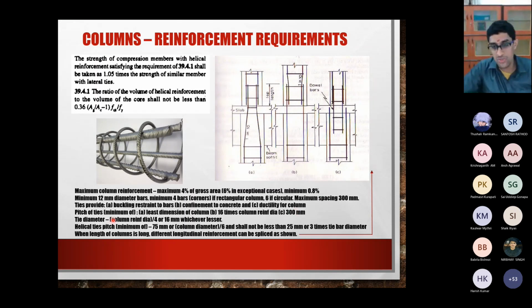So if it's a 600 mm length side, instead of giving, say, 2 bars of 16 mm diameter, you may give 3 bars of 12 mm diameter, so that the spacing is also taken care of. And there is no point giving 3 bars of 16 because it will be too heavy. So you can make it 3 bars of 12. These are all small adjustments that you can make.